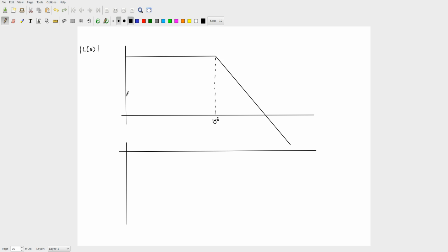This is modulus of that. All right. So this value is going to be A0 by K, and A0 by K is 1000. Okay. So can you calculate what this frequency is? Approximately what should it be? This is falling off at minus 40 dB per decade. If I call this omega 1 corresponding to P1, what should this be? No, this should be square root of A0 by K into omega 1, right?